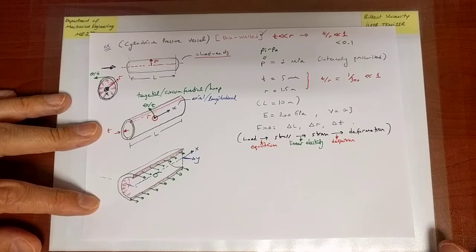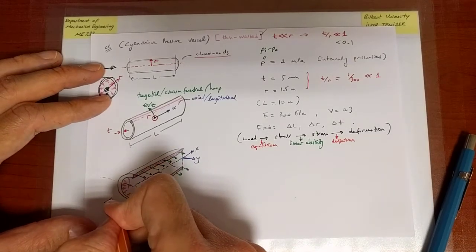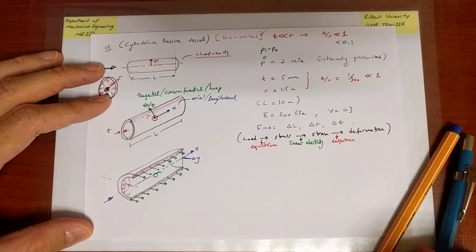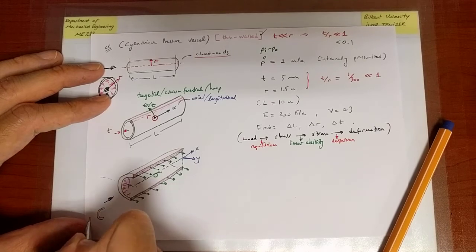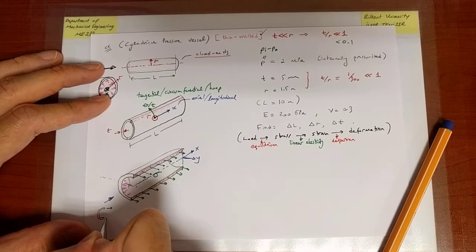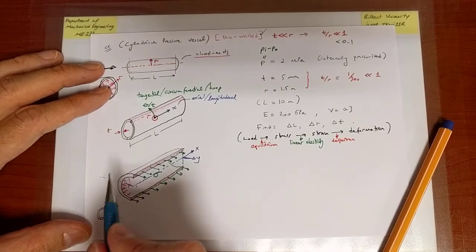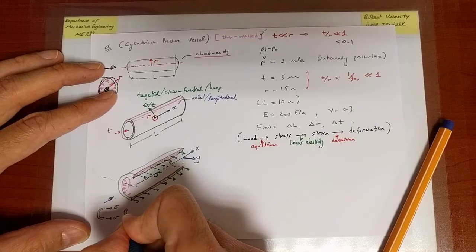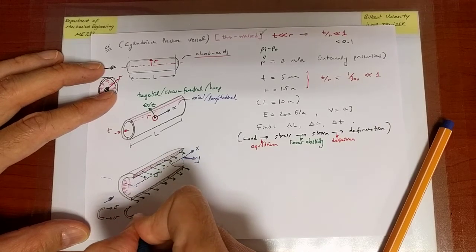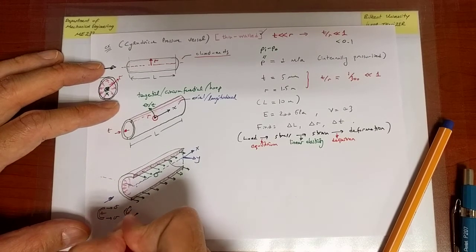Locally, my coordinate system is directed along the y direction, but notice that if I take any other cut, for that matter, presently the cut I've taken, when I look along the x-axis, looks like this. Pressure pushes in that direction, and the normal stress sigma acts in that direction. I could have sliced it at another angle. In that case, I would have observed a cut like this, and the normal stresses opposing the net force due to the pressure would be situated in that direction.